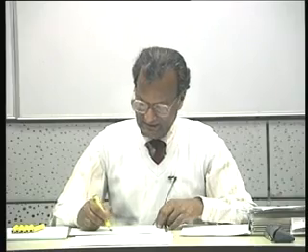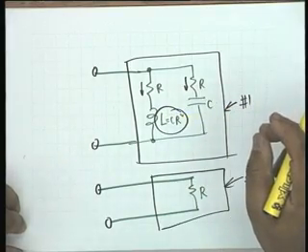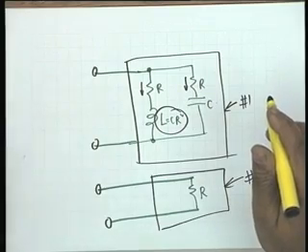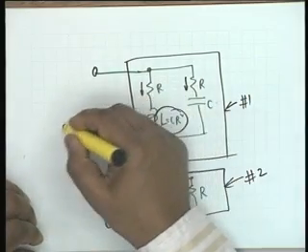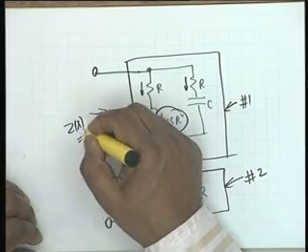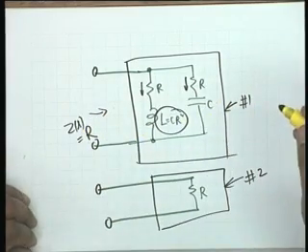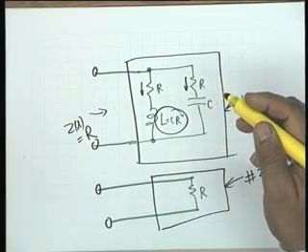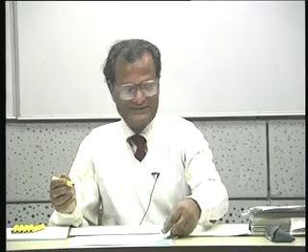That is correct. It is because of the special value, the resonance frequency. It makes it resonate with all frequencies. One of the poles cancels with one of the zeros, always. If you find out the input impedance, it is identically equal to R. So the poles and zeros cancel each other. If we short the input terminals at 0 plus, would it be correct? Try it out. If you can do it, that would be news.